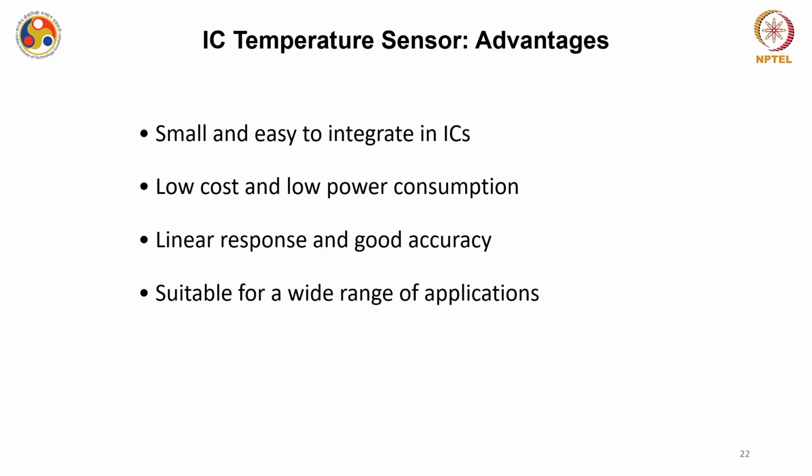The advantage of these IC temperature sensors is their small size and that they are easily integratable with the existing CMOS technology, okay. And some of the IC sensors are actually fabricated based on TTL technology, so they are also compatible with that particular technology, okay. The low cost and low power consumption of these IC temperature sensors are very fascinating, and batch fabrication actually enables them to be utilized in low power or low cost devices, okay.